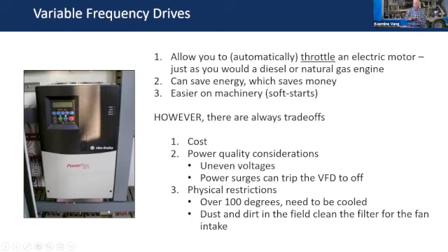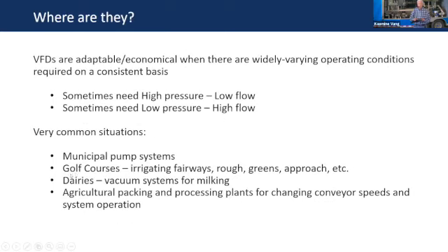If you have no reason to run other than full speed, they're not going to save you any energy at all. In fact, you're going to lose about 4% efficiency through the VFD. But as long as you have a reason to slow that pump down part of the time, it can save tremendously, and we'll demonstrate that. They come into play pretty well if you have widely varying operating conditions, different flows and pressures, maybe you need high pressure, low flow, or low pressure, high flow on a consistent basis.